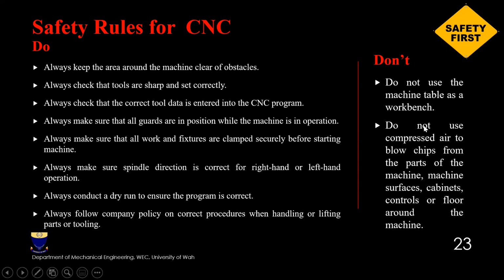And the don'ts in this slide are: do not use the machine table as a workbench. It could be hazardous. Do not use compressed air for blowing chips from the part, machine surface, cabinet, controller, or floor around the machine. It could also be hazardous in the way that the compressed air has immense pressure that it can blow chips that can harm yourself and others in that area as well.